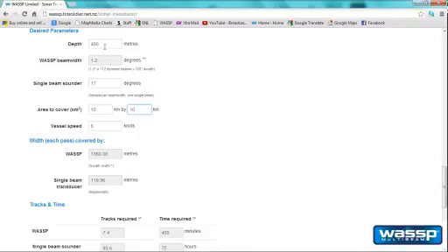So in 400 meters of water depth, each pass of the WASSP will be 1.36 kilometers wide. Just incredible. That's how quickly you can map an area. So as you move along, the corridor that you map on the seabed will be 1.36 kilometers wide in 400 meters of water. The single beam transducer, however, has a footprint coverage on the seabed of basically 120 meters, 119 meters. So we're getting better coverage on our single beam transducer.